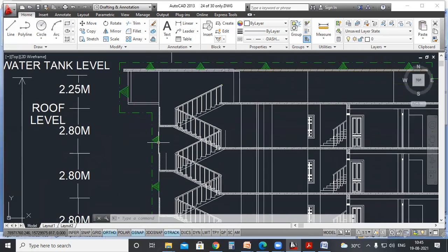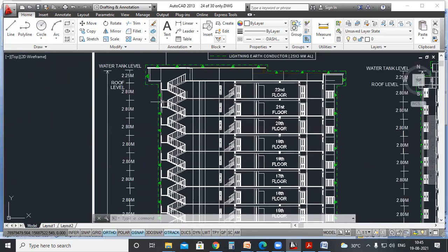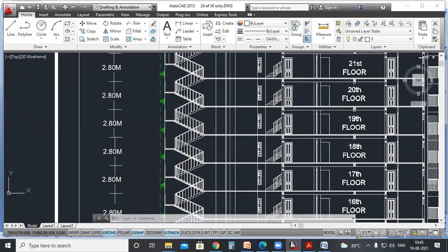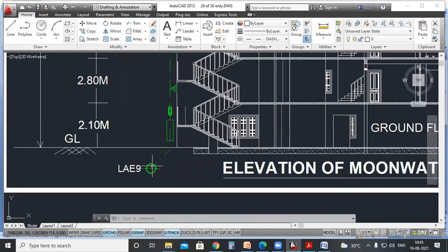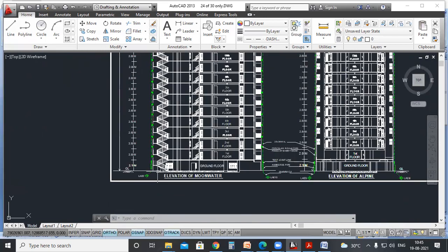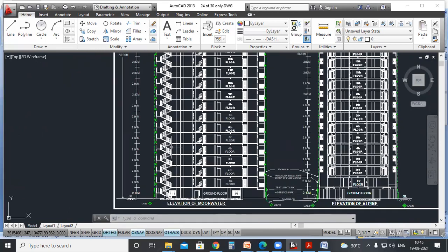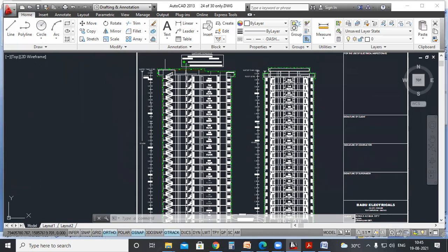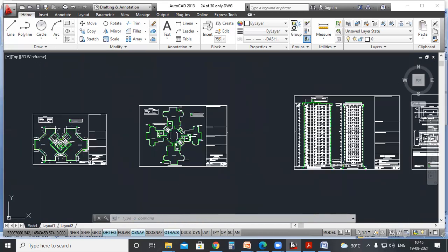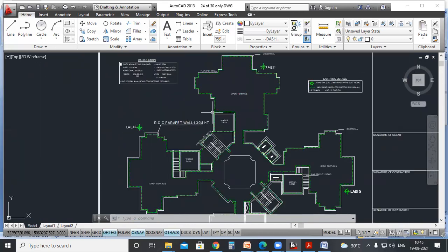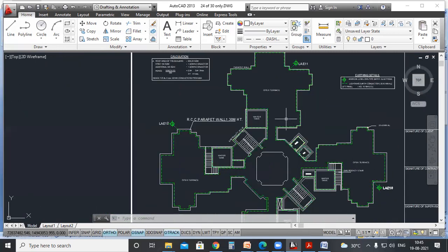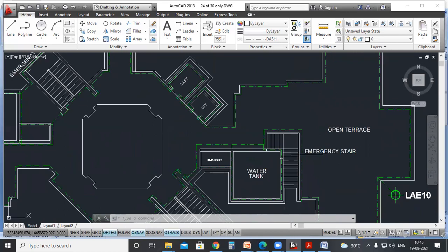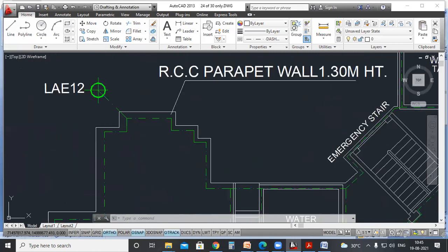We have to make sure that down conductors are provided at equal intervals. Then it is safely earthed to the earth pit. Normally we would provide pipe earthing for the lightning arrestor. So this is the plan drawing. You can see it is covering all the parts, all the edges and corners, and it is taken down at frequent points.